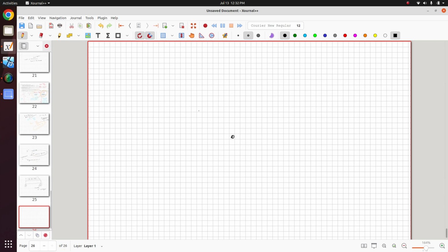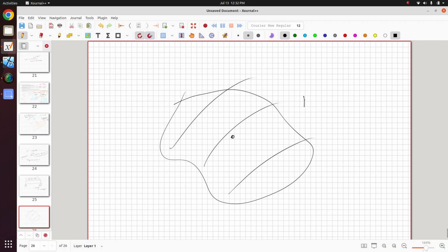Find the node, look at the surrounding mesh, ask yourself why is that region a mechanism? And the reason you should do this is because somewhere else in the model is causing the mechanism. So in this example, what we did a lot was we used normal modes a lot.